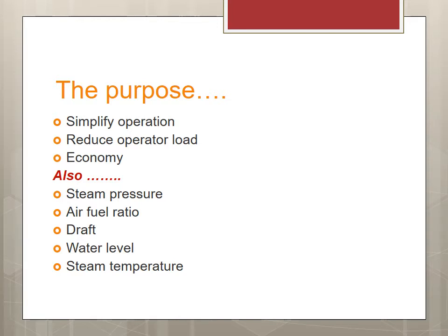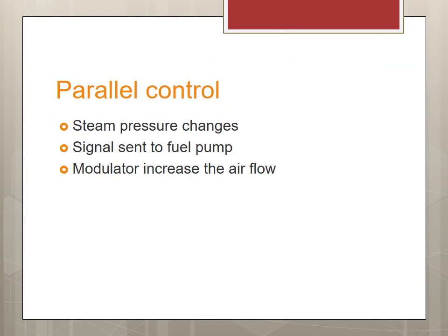Also, the system will be able to control the water level and add some makeup water. It can also monitor the water quality to tell you that maybe it's time to do a purge or a system blowdown. And as we control the steam pressure, we can control the steam temperature. We know they go together. In this case, we have parallel control where the steam pressure is our output point. We send the signal to the fuel pump, and we modulate the air coming in based on the fuel pump using a cam. I will show you how.